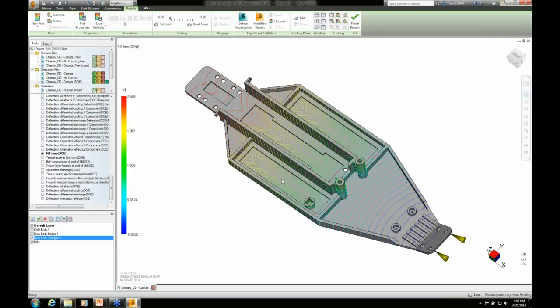I've got a little bit of hesitation. They get further apart, I'm starting to racetrack, or the material is speeding up. So you can see here towards the end, the material is moving very, very fast. I've got these little cutouts in my part. I can see now in these cutouts how much hesitation I'm getting, how much faster it's moving down the rib structure. All of this is critical information to have.